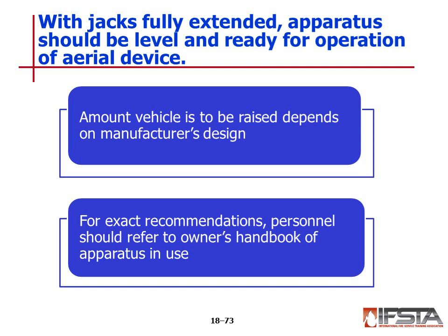The amount the vehicle is to be raised depends on the manufacturer's design. Some stabilizers are designed to have all apparatus tires lifted off the ground. Some are designed to lift only the rear tires. Others are designed so all tires remain on the ground. For exact recommendations, personnel should refer to the owner's manual of the apparatus.